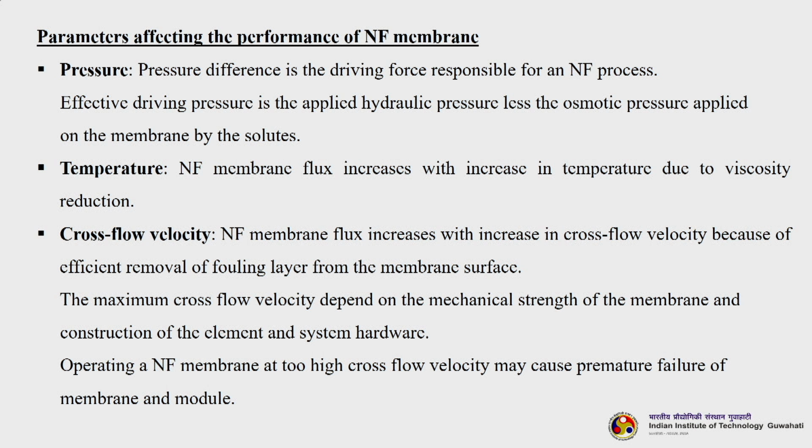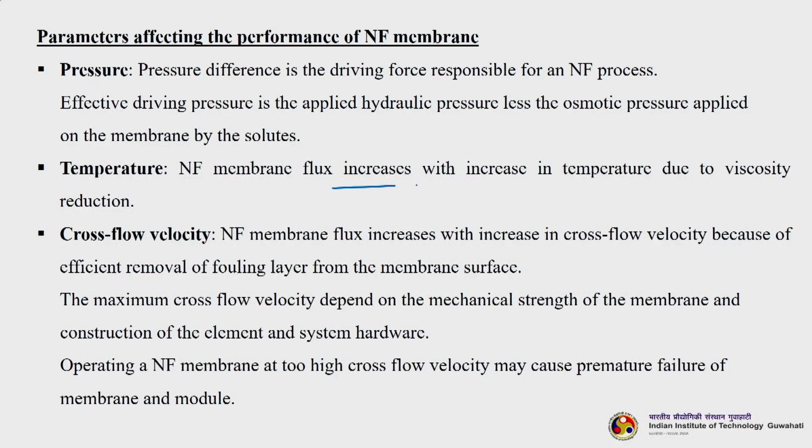Let us now understand the different parameters that affect the performance of a nanofiltration membrane. There are various parameters, we will see one by one. First and foremost is of course the pressure. Pressure difference is the driving force responsible for a nanofiltration membrane. The effective driving force is the applied hydraulic pressure less the osmotic pressure applied on the membrane by the solutes. Temperature: nanofiltration membrane flux will increase with an increase in temperature, because when the temperature increases, the viscosity is reduced, and that is why the flux is enhanced.